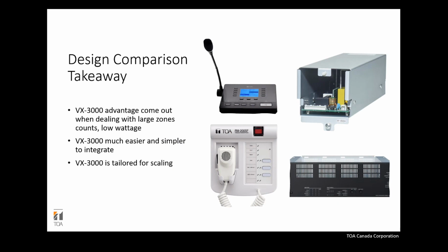So what is the general takeaway from the VX3000 system? Scalability. You can go up to large zones depending on what you need. Low wattage, multiple zones. You can customize it as much as you want. It's much easier and simpler to integrate because it's using TCP/IP. You can even connect them with each other over daisy chain. No need for a switch. There's some trade-offs with that, but you have the option.